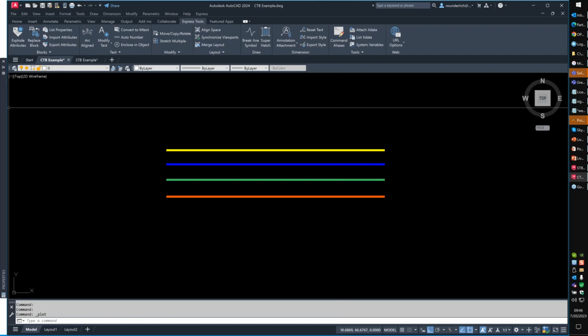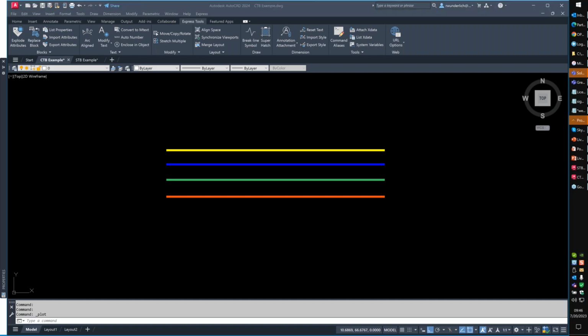All right, Jimmy, you've probably got a bigger problem if you've reset to default and the problem persisted. You've even started with a new profile. We may have to play with the graphics card configuration. Yep, try the command CELTYPE to set by layer for the color issue. Yep, that does work. I did cover another webinar on acad.lsp, and the things that I have set up in mine.